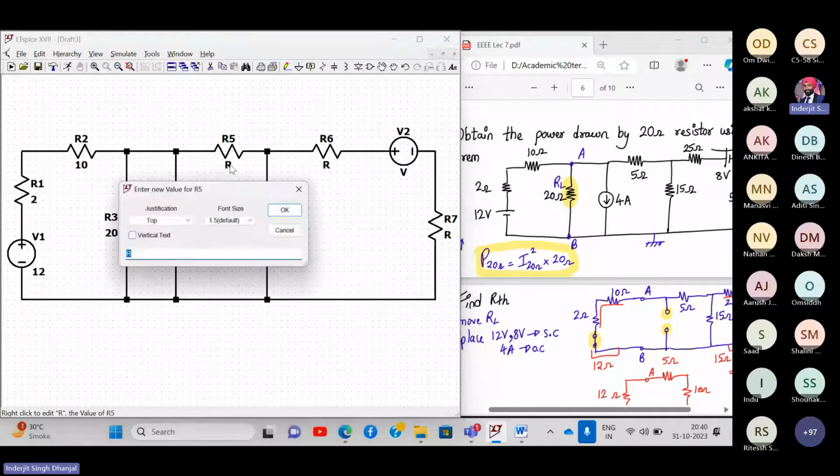Yes, sir. Now the current source, we open circuit it. So like this, open circuit. Even if you remove it, if I open circuit the current source, it will be gone. So let's remove it only. And I'll open RL. I'll remove the load RL. So this is my load RL gone. Did you understand this much?